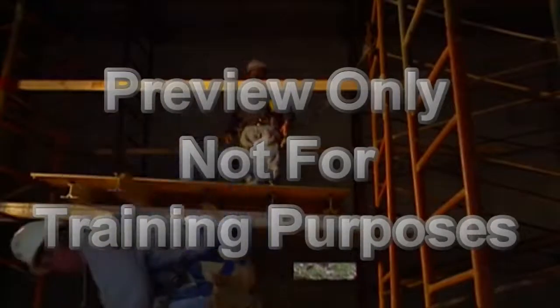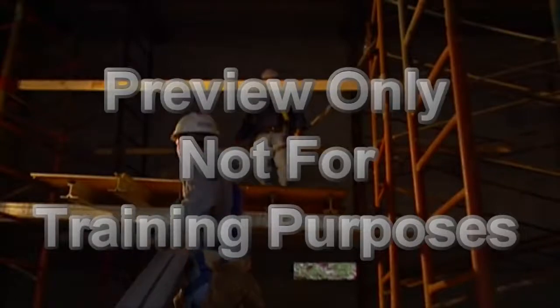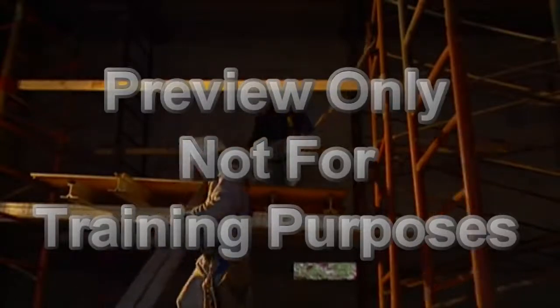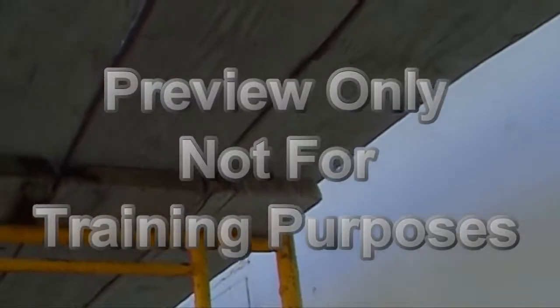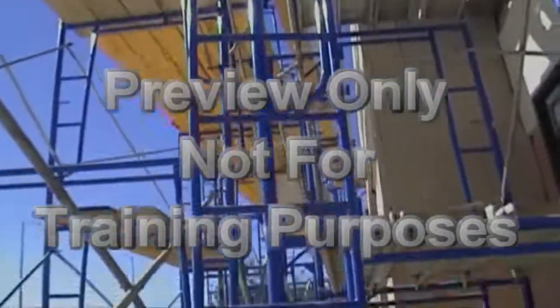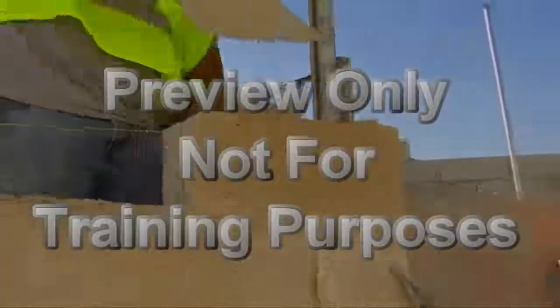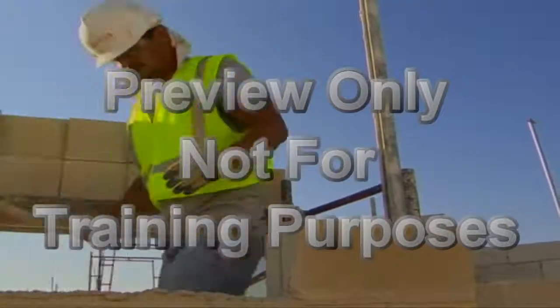When moving platforms to the next level, the existing platform must be left undisturbed until the new end frames have been set in place and braced. There should not be more than a 14-inch gap between the scaffold platform and the structure being worked on. An 18-inch gap is permitted for lathing and plastering and masonry work only.